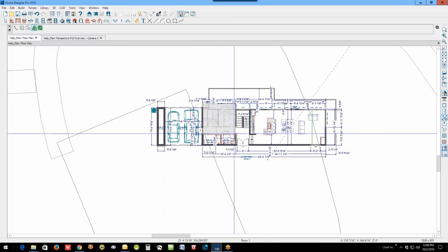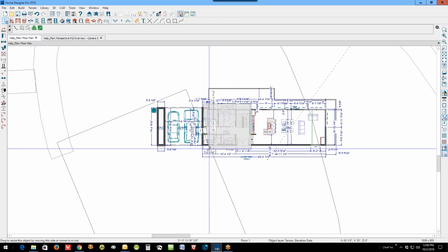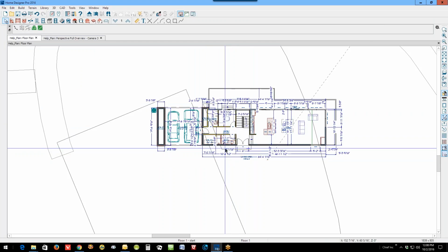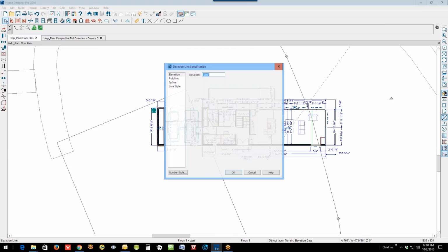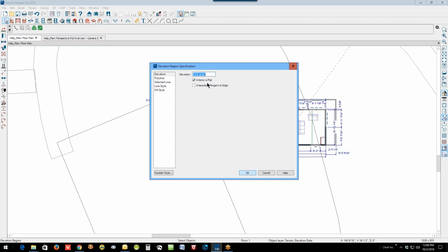In this area, now you don't want these things overlapping, so I'm going to move this over a little bit so that it's not overlapping the adjacent terrain region. And if this is minus 200, I'm just going to have to guess, since I don't have your topography. We'll set this at minus 100 as a starting point.